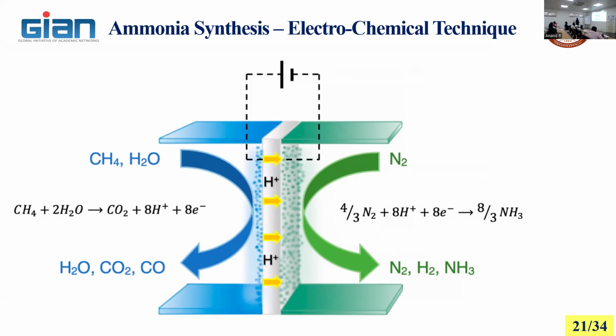So you can go for Haber-Bosch or the electrochemical method, depending on the required quantity of ammonia, because you cannot use the electrochemical method to produce a few million tons immediately. It takes more time. About 100 kg per day or maybe 1 ton per day is possible. In Australia, Russia and Japan, people have started working on million-ton capacity, but it's not commercialized till now.